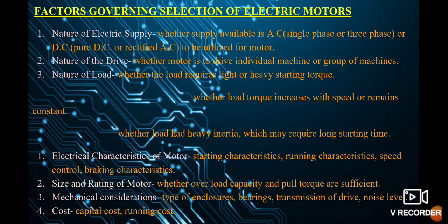Next one is the factors that are governing the selection of electric motors. So, the nature of electric supply. Whether the supply is AC or DC, that is single phase or three phase AC, or pure DC or rectified AC, can be utilized for the motor.